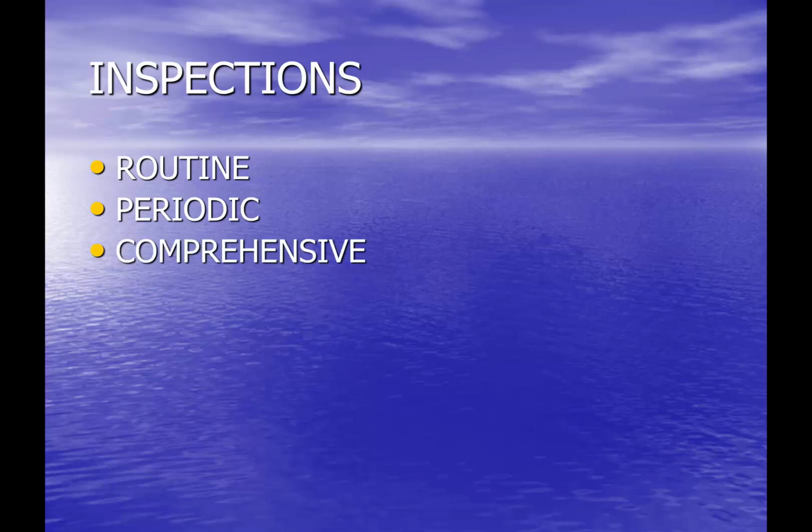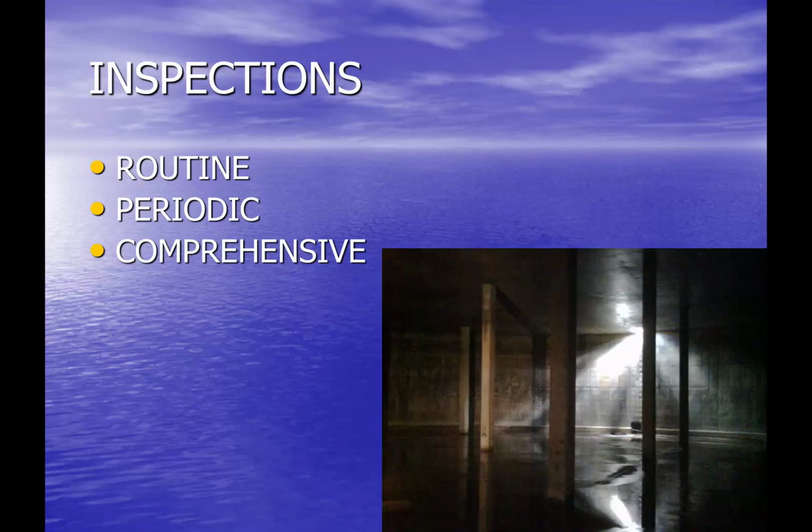And then a much bigger one is going to be a comprehensive inspection. This is now an inspection where we're going to get inside the reservoir. We're going to do some level of detailed evaluation of the interior of the reservoir, as well as continue to look at the exterior. Timing on these is not something that is clearly prescribed. I've heard it suggested that you want to do this annually for elevated tanks or every 3 years for other tanks. I'm not going to say that those are hard and fast numbers.